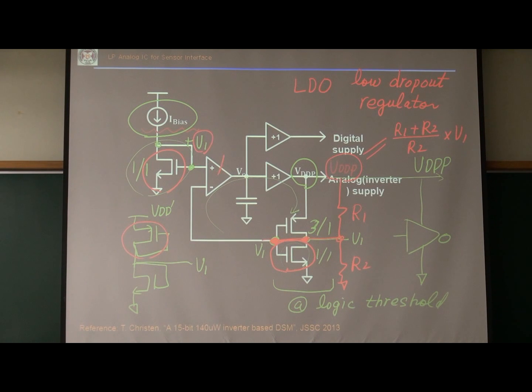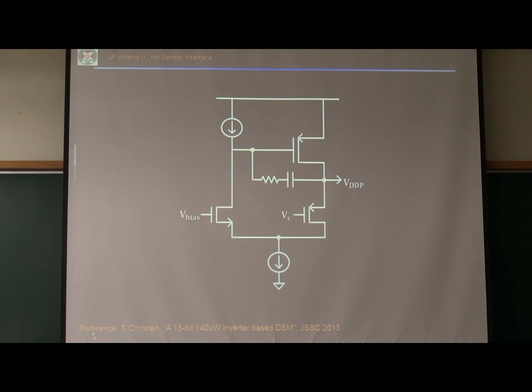This is a differential amplifier, and those are source follower circuits. So forget about this digital part. This has AC gain of +1, so you can see this source follower can supply large current. This is actually a source follower circuit.